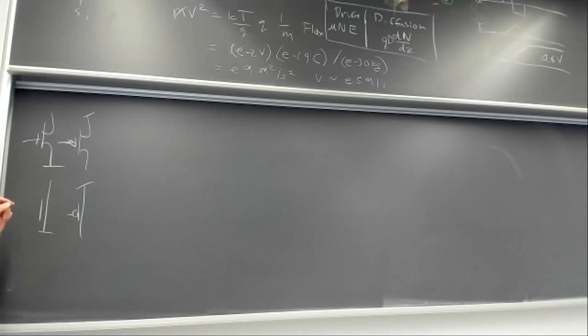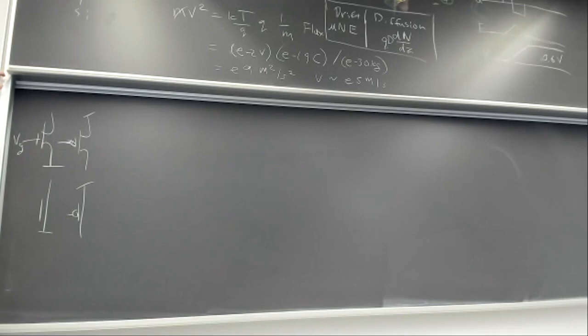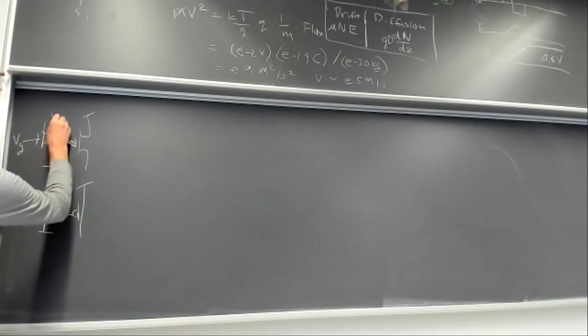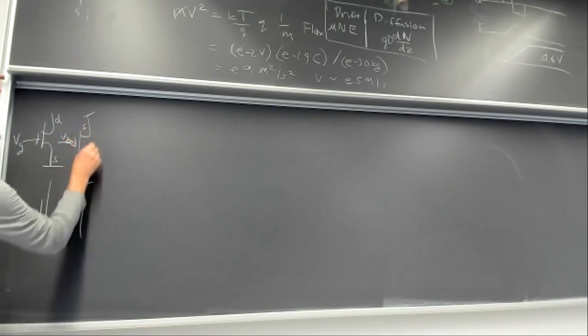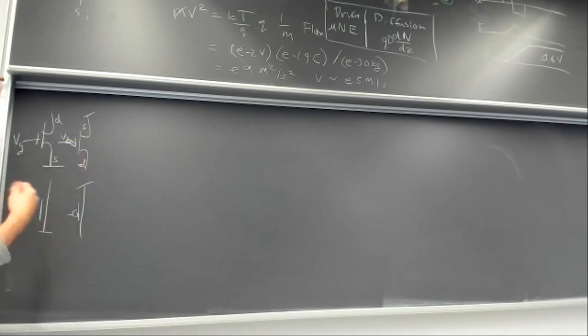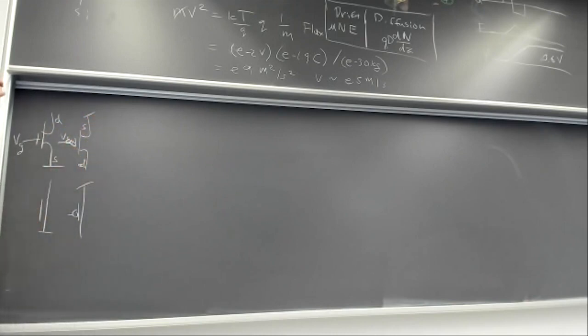It's clear, right? That's a symbol for this cross-section thing up there, where this is the gate. Which is the source end of this NFET, the bottom or the top? Where do the electrons come from? Bottom, right? Okay, so this is the source, and they fall out of the drain. And now for the PFET, this is the gate. Where do the holes come from? This is simpler, right? Holes go from high voltage to low voltage, because they're positive charge. So it's really easy. The source is always the higher voltage. It's easier because they're positive, right? They fall from high voltage to low voltage in the direction of the electric field.